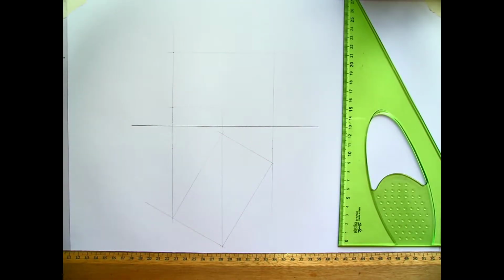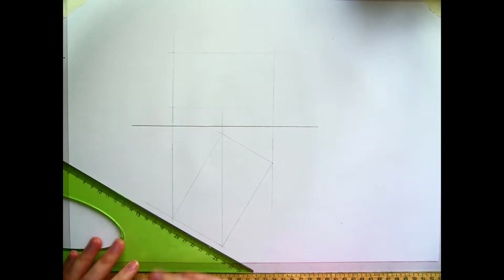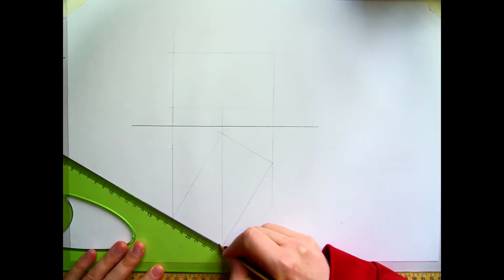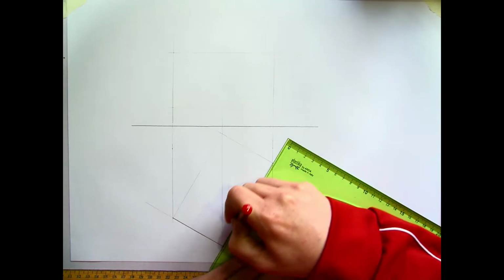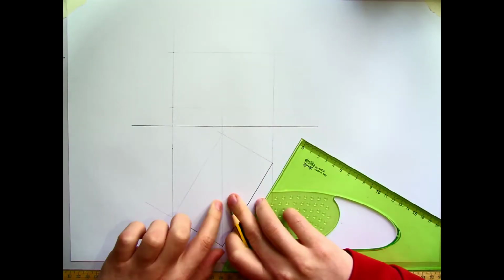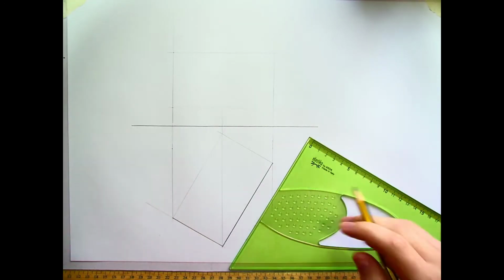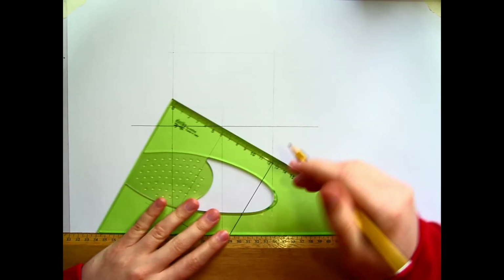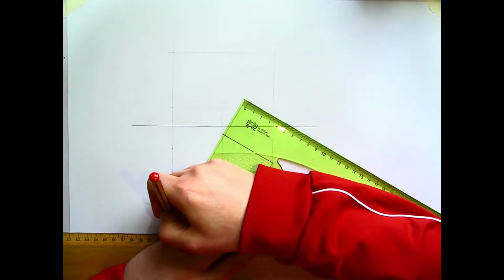So I've started to set up this question. I kept it down to the bottom of the page. I'm using an A3 page, so keep it quite low if you're doing that. Line going this direction at 30 degrees, and this line here is at 60. And all I did then is measure 55 millimeters either side and draw two vertical lines until they intersected the lines at 60 and 30 degrees. And then coming back in towards the center.